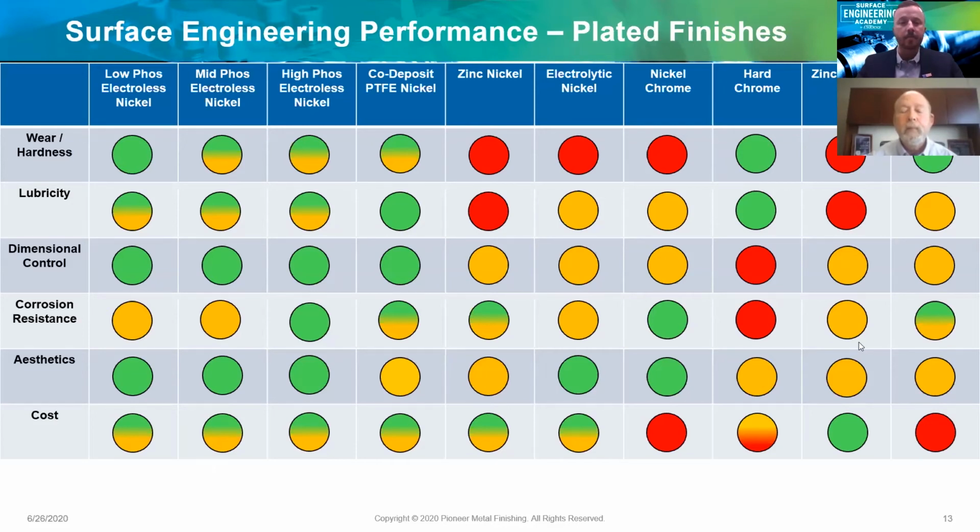Perhaps there's an application you have that is cost sensitive, and it's an interior application, and today maybe you're applying a thin layer of electroless nickel or even a nickel chrome or a zinc nickel, and geez, that might be overkill. And comparing that versus, say, just a down and dirty zinc plating process. So really designed to get the audience to think about the various concepts at work here as you go about either designing new programs or revisiting from a continuous improvement perspective your existing portfolio.